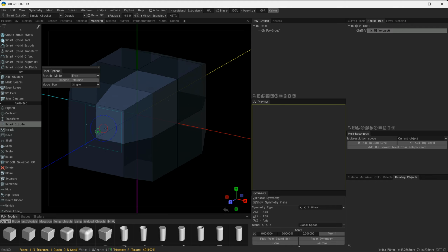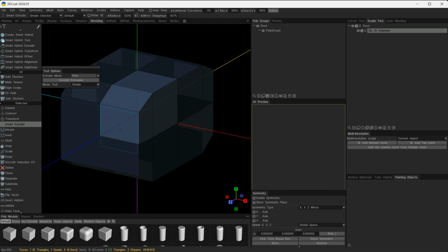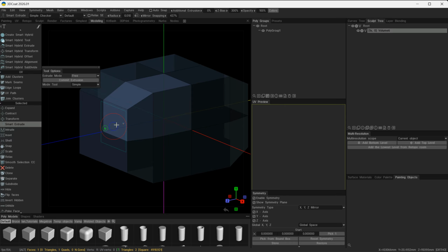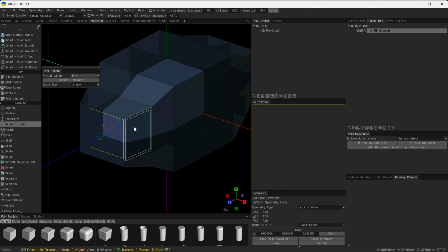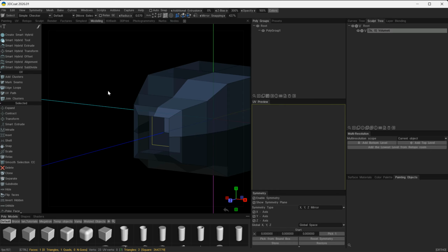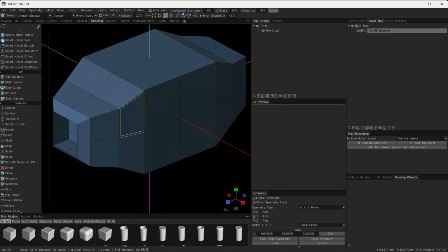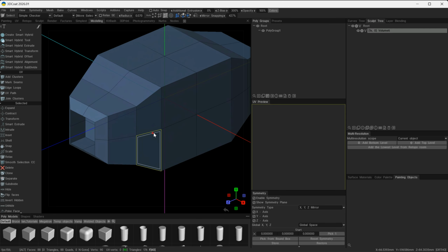The same applies with the mirror, that if I'm pulling these too far apart I'm going to break the symmetry with that, so I do have to be careful. Alter your mirror snapping on there to help fix that issue, and then we can keep extruding and using this tool to do that. So let's escape that tool, drop the selection, mesh, apply, virtual. Just starting off with 3 faces, I'm able to quickly create this type of object.